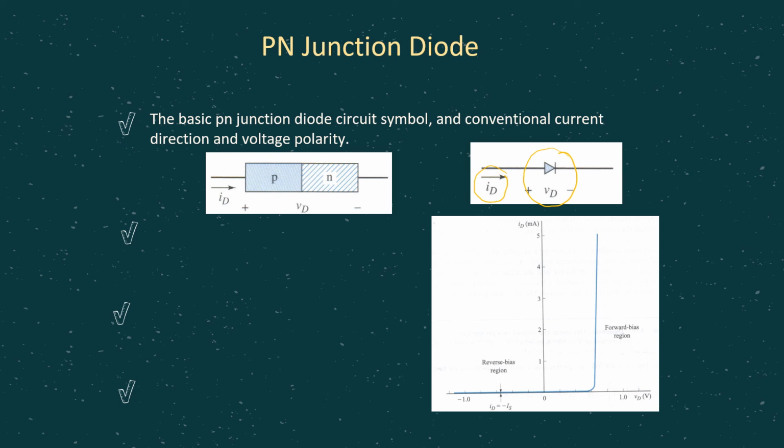Okay, so you might see much better when we refer to this IV characteristic, ID versus VD. When VD is positive, at the positive region, here we are referring to the forward bias region. As you can see from this region, initially the current is still zero, although we are talking about the forward bias region where the depletion region becomes narrower, remember, where diffusion of carriers is possible. But initially there won't be any current flow.